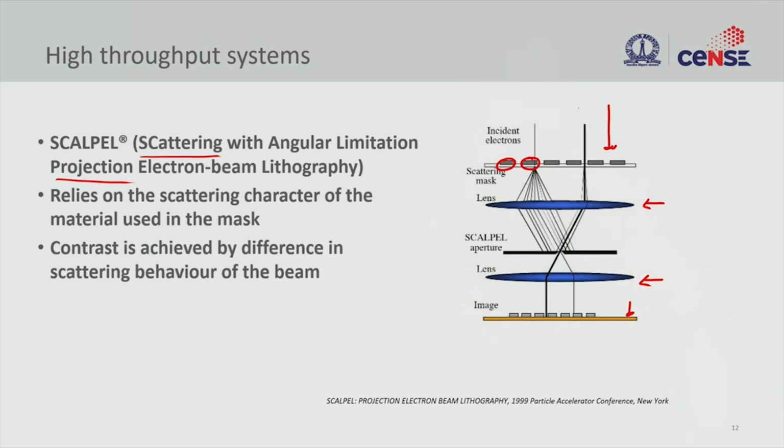But recently people have come up with multi-beam writing, right. That is the most interesting part, where instead of using a single beam, you will use multiple beams, and these multiple beams will have individual deflectors, and these individual deflectors can write multiple areas. So what you are trying to address is you are going to increase your write field, right.